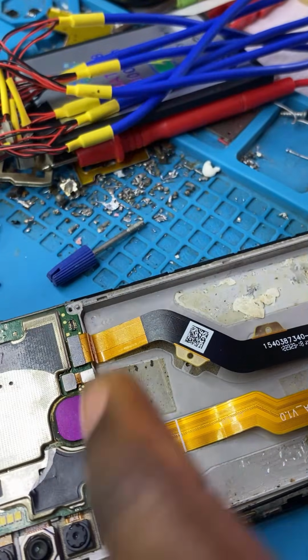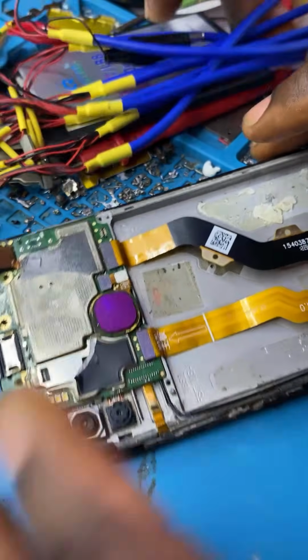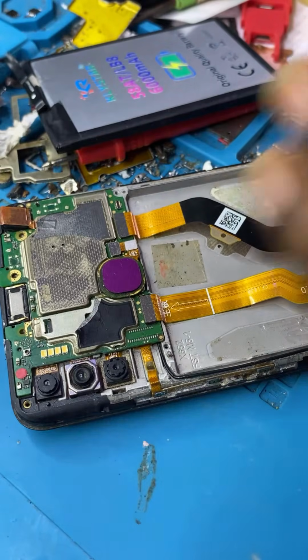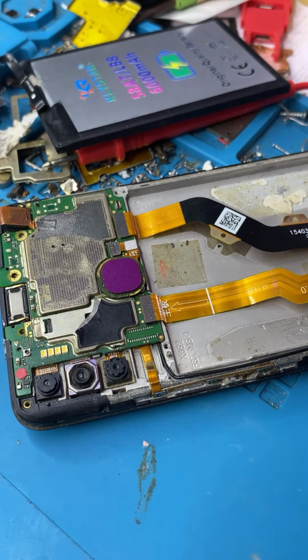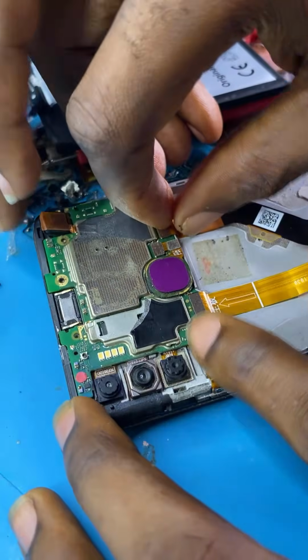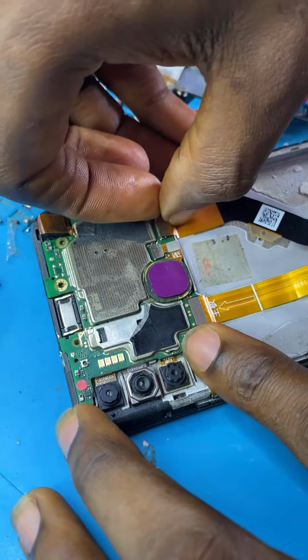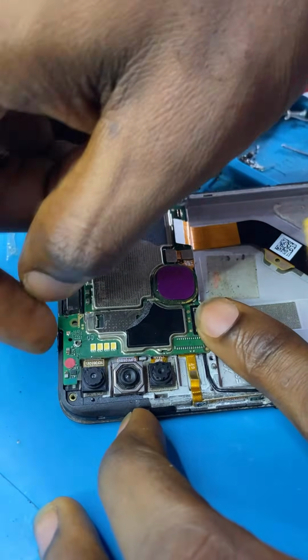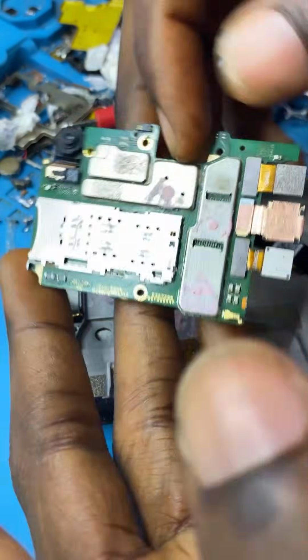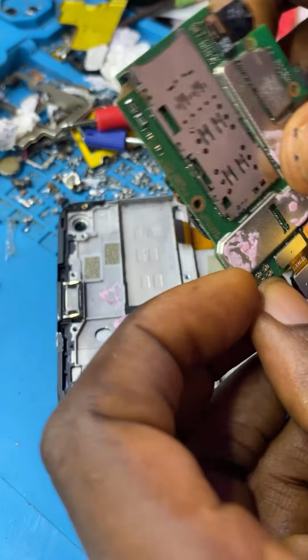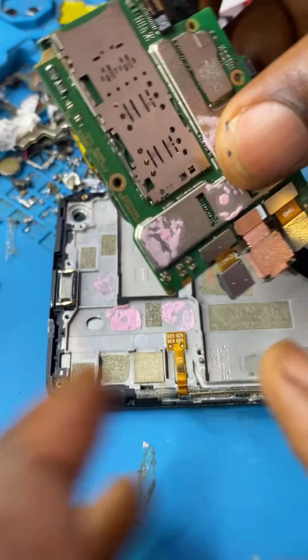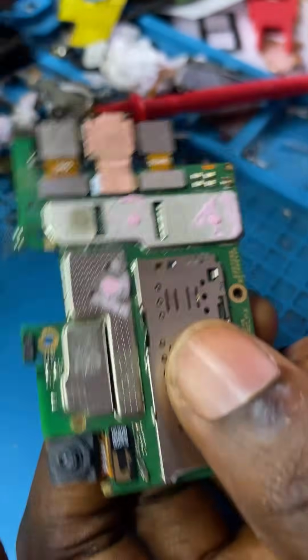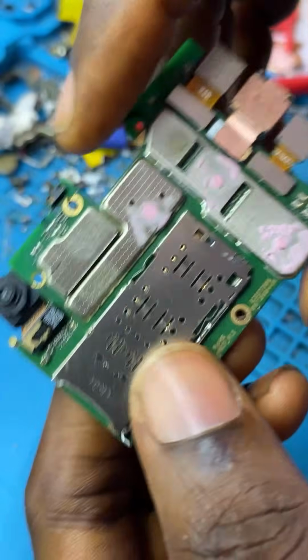So with our DC power supply, it's clear to me, and I'm sure it's clear to you guys, that the problem is from a fuse resistor right here on the PCB. Let's go ahead and fix it. If we fix it and we still have an error, I'll still go ahead and troubleshoot so we can finally fix the phone. You have to fix everything. Before this phone comes to me, they have already worked on this phone, so have that in mind.